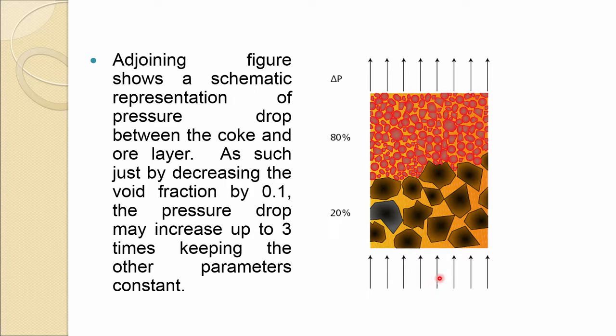You have to put in more air pumping power, and not only that, it also affects the reduction and the passing of the gas, utilization of the reduction power of the gas, and the heat exchange between the material and the gas.